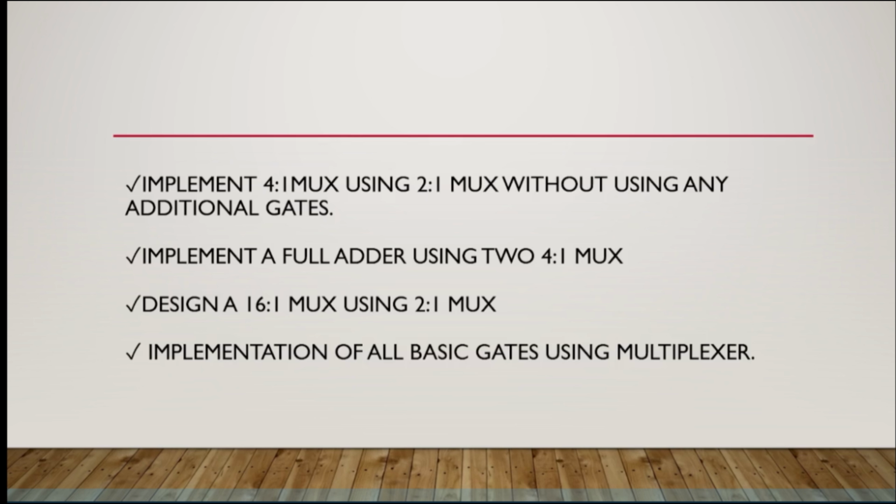Basically, when you come to combinational circuits, how you are asked in the interview is like this particular question. If you see here, implement a 4 by 1 mux using 2 by 1 mux without using any additional gates. If you know how to implement it, then you can just convert it into code, right? So these implementations are in this manner.